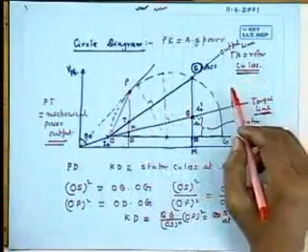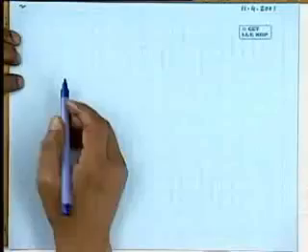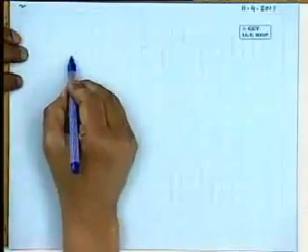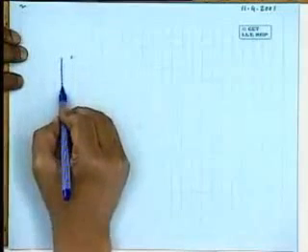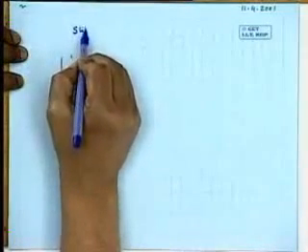But as I told you, like the earlier case of the simplified equivalent circuit, here also one can draw a slip line and further reduce the calculations for fixing up the point, and can read the value of the slip very quickly. That I will just tell you how to do it. So now your circle diagram will look like this one, that is the slip line.